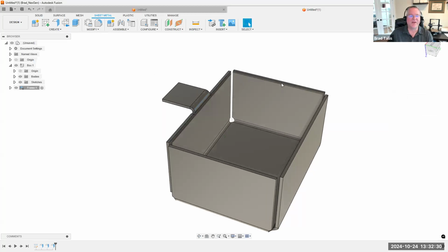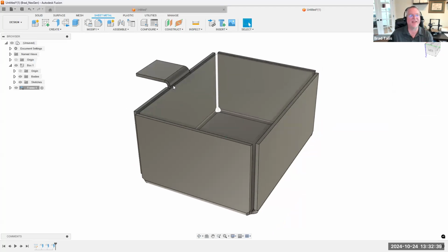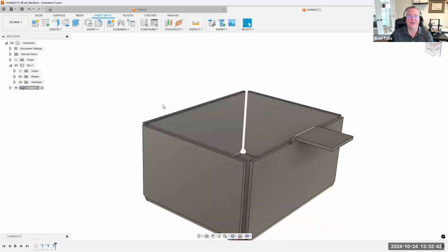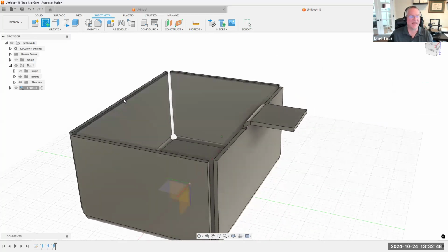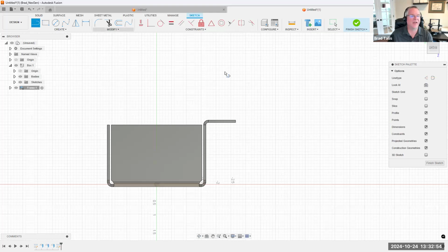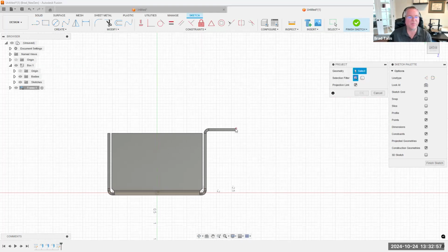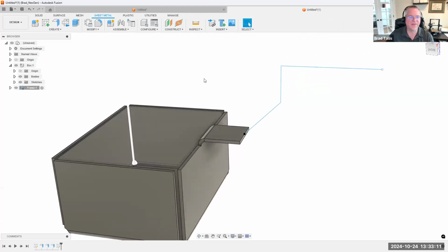Okay, so we've talked about using the flange for creating the original sheet metal part, using the flange to create the walls, using the flange to then create like a tab or something like that. Here's another method you can use. If I come in here and I create a sketch, let's just pick maybe like that sketch there. And I'm just going to project this point right there. And I'm just going to draw some weird shape like this, for example. A single line, well, I guess three lines connected, but no thickness or anything like that.